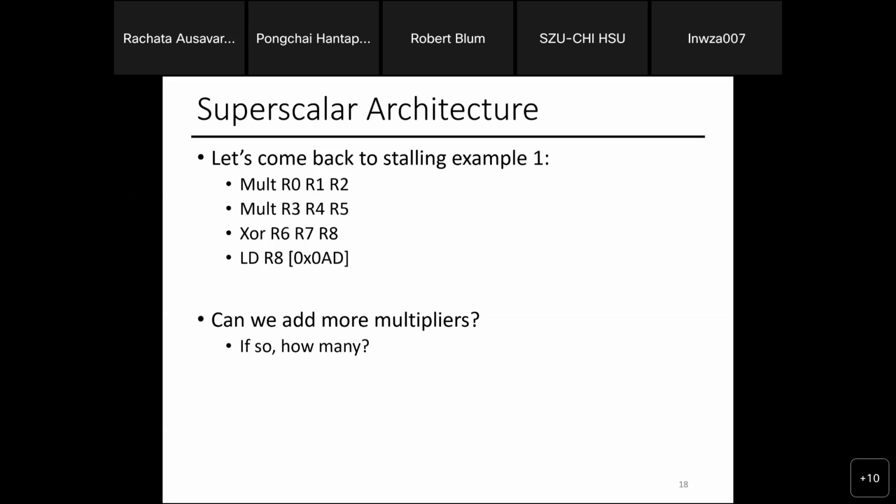Basically, it's a design where you have a fetch unit, decode, execute, memory, and write back. There is this thing called the instruction window. The fetch will always keep fetching. I don't care what's happening in the pipeline, I just keep adding things into the window. Then the decode takes the top one, because the top one is the oldest, right? Take the top one, figure out what to do, feed it to execute, and it would aggressively go through the table so that if anything is empty, and if I can feed it to this execute unit, the decoder will do it. Yes. What is the path limit?